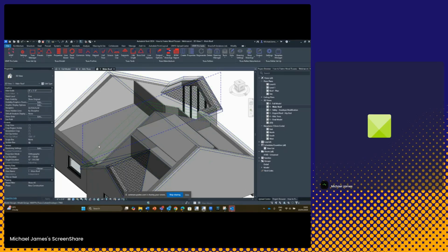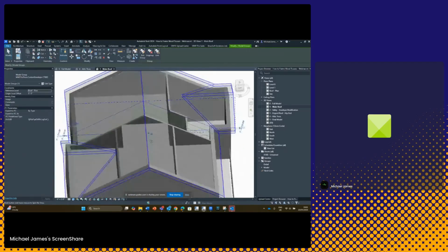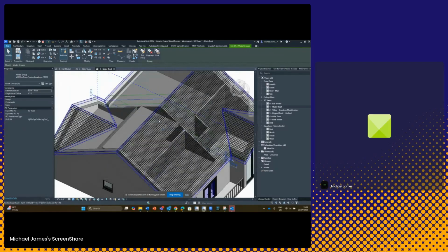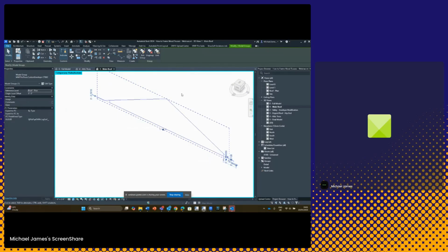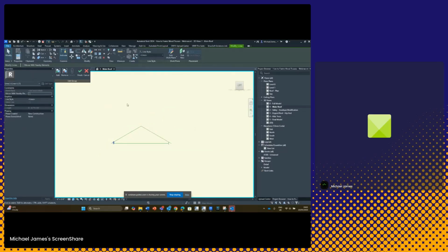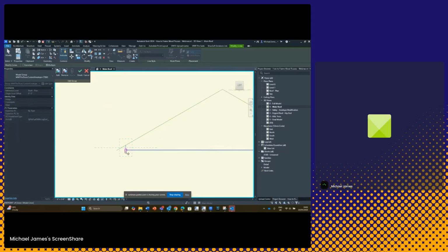All right. So the best profile we have is actually the middle one. So I'm going to select the middle profile. I'm going to go to Edit Group. So I'm going to isolate it first. Edit Group. I'll just remove the excess there. If I wanted to generate this as an attic truss, then we've seen the process, guys. I'm just going to quickly go through that now again, but I'll try and keep it as quick as I can. Okay, so I'm going to copy this line from the left just to the center,